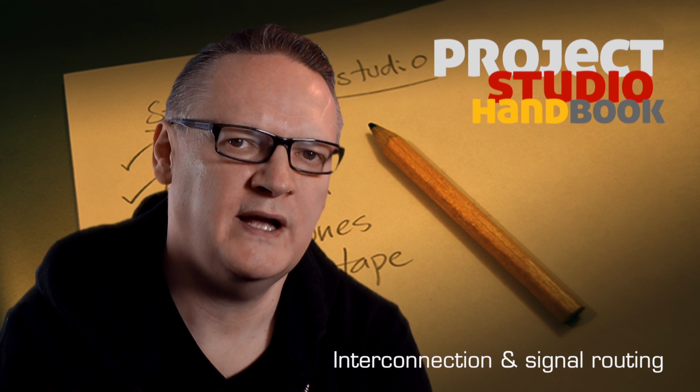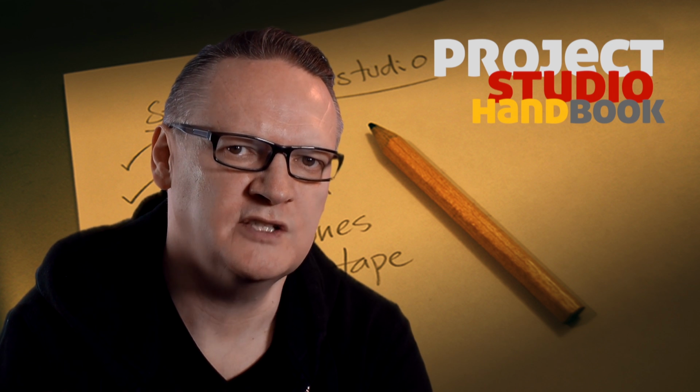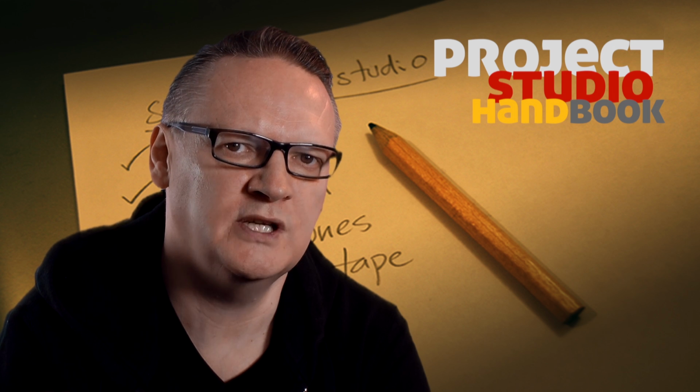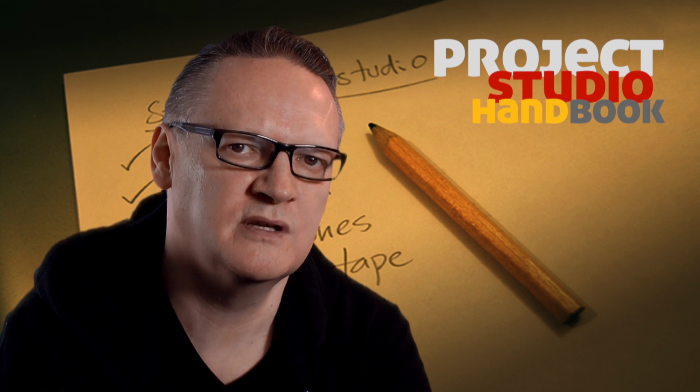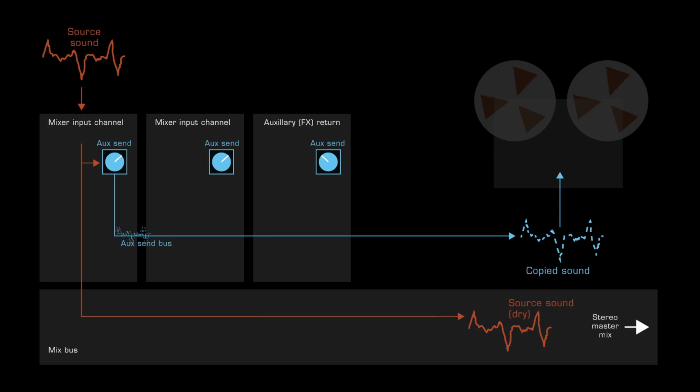There are a number of ways to create a copy of a source signal, but the process was first achieved by using an auxiliary send bus. The source signal travels down a mixer input channel strip, and an auxiliary send bus creates and sends a first generation copy to a mono or 2-track tape recorder dedicated to creating the delay.